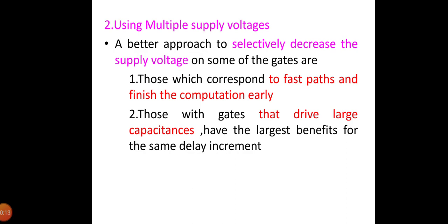This approach can be extended to lower the power dissipation of the circuit. For instance, every module could select the most appropriate voltage from two or more supply options. Even more, multiple voltages can be assigned on a gate-by-gate basis. Consider, for instance, a digital system which consists of a data path block with a critical path of 10 nanoseconds and a control block with a much shorter critical path of 4 nanoseconds, operating from the same supply voltage of 2.5 volts. Also assume that the data path block has a fixed latency and throughput, and that no architectural transformations can be applied to lower the supply.